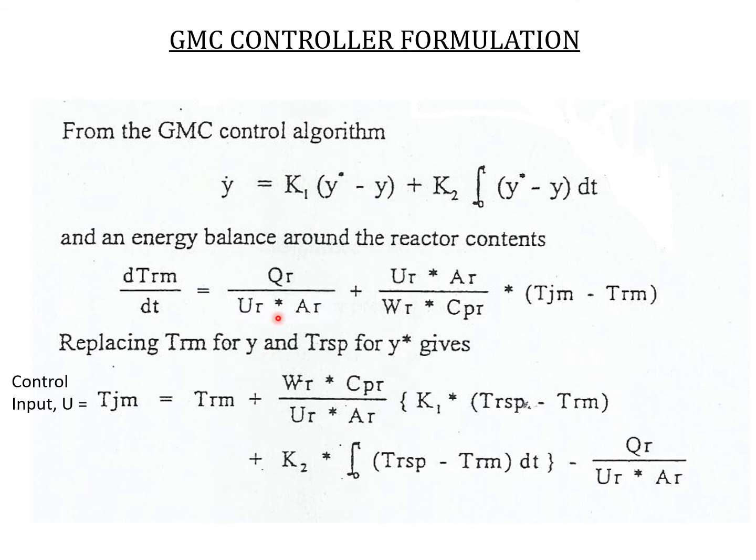and you have the K1 tuning, K2 you have to tune, the set point we know, whether it be a profile or one direct number, it doesn't matter, and minus this value. So all these values depend on the parameters of the model. So we have them, we can use them. We do not have to estimate. The one that is most probably more difficult for us to get is the QR, because this is the heat release. It is something they are not able to measure. Normally it's not simple to measure the heat release. So we may have to estimate it, as I said just now.